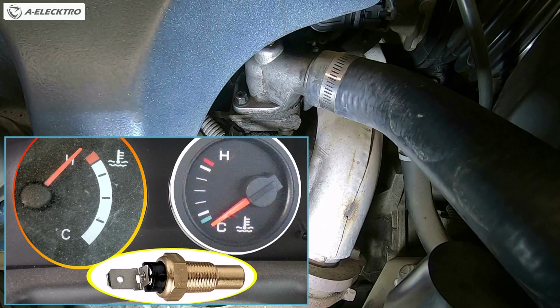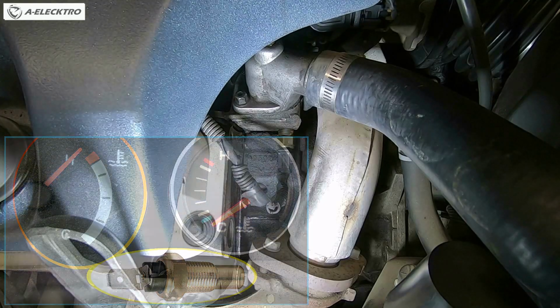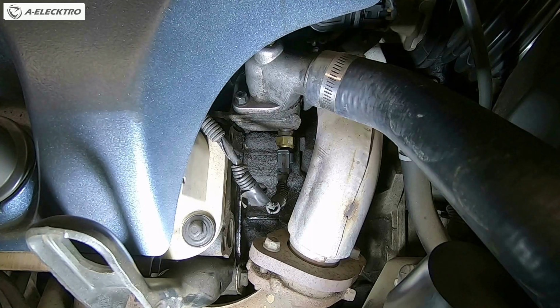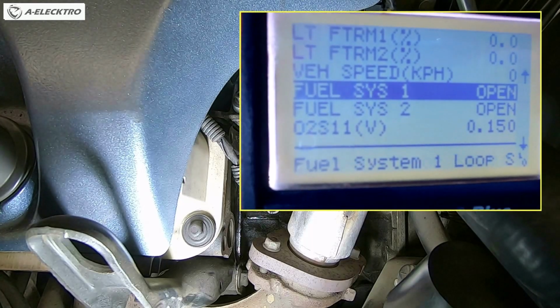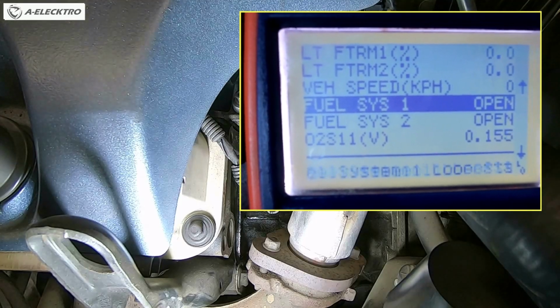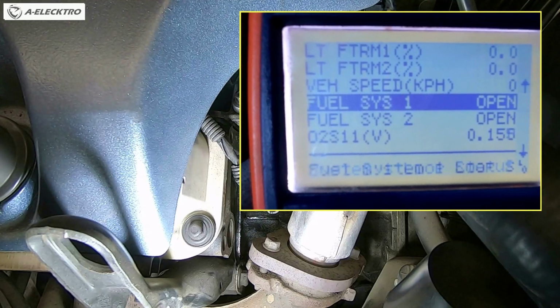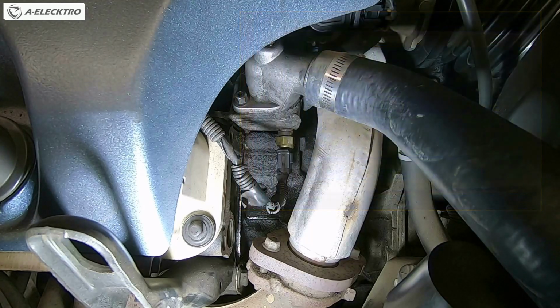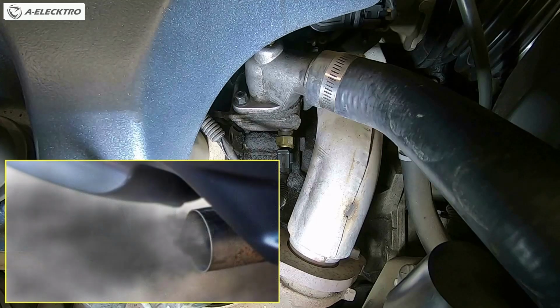When the coolant temperature sensor is constantly reporting hot engine values, the problems are also significant. One of the most obvious symptoms is difficulty starting the engine. This is because the computer receives conflicting information, which can result in a very short pulse width in cold engine situations. If the engine manages to start, we are likely to experience an unstable idle, which can affect the overall